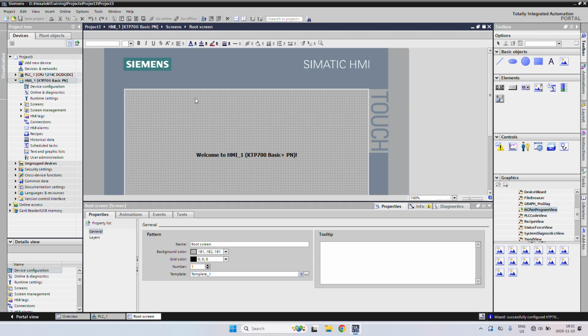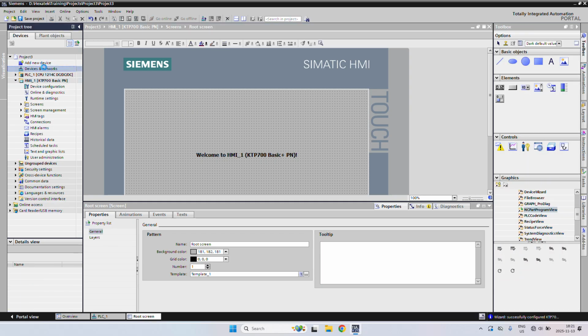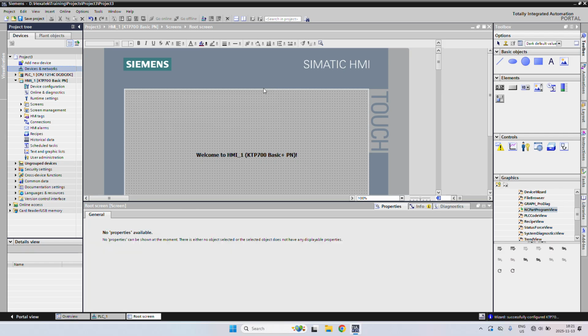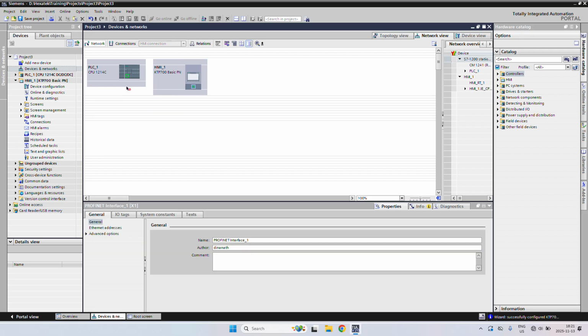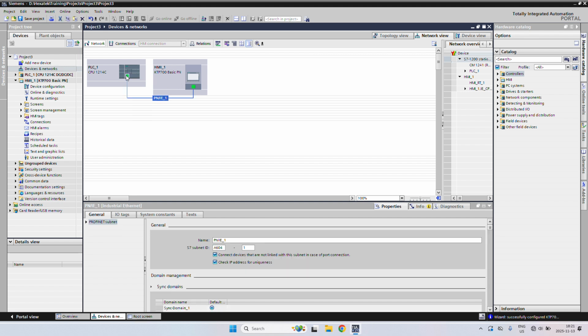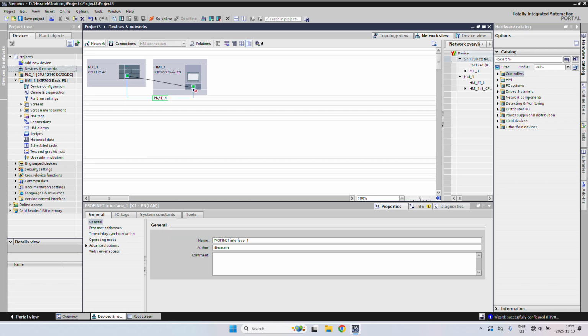While adding the HMI we can add the communication details, or here we can select. So now it is communicated. If the PLC and HMI are both Siemens, this communication is very easy. Simply we have to drag from this point to this HMI communication point.